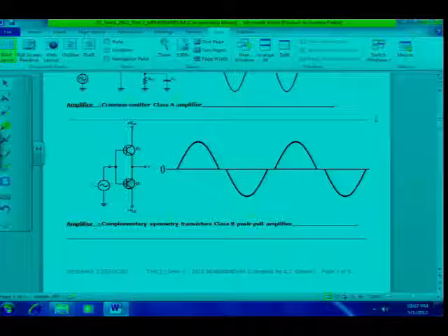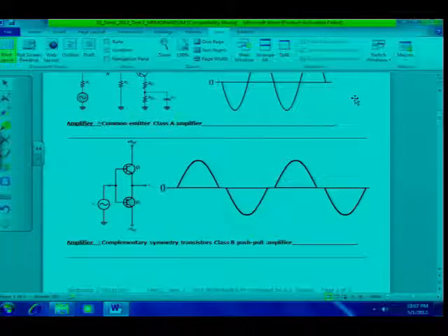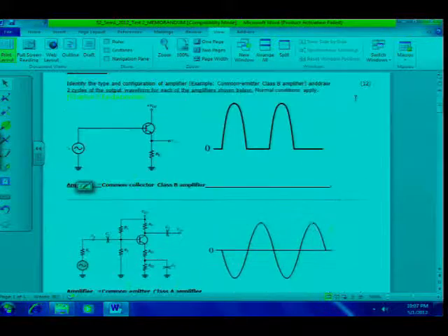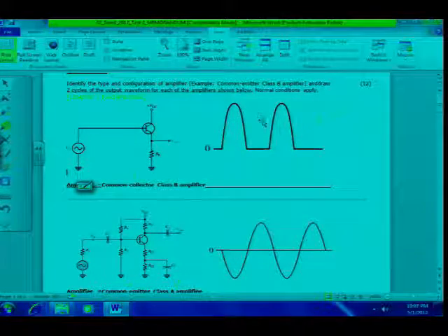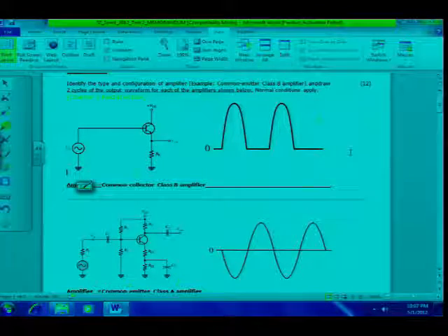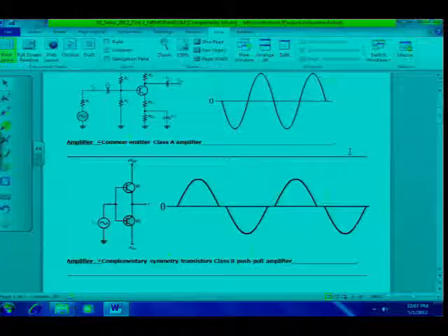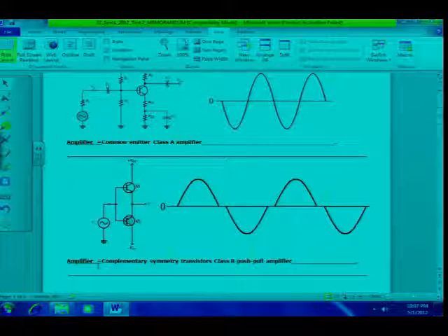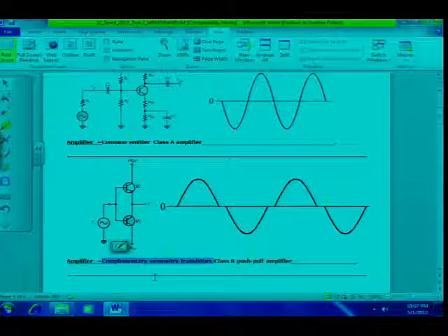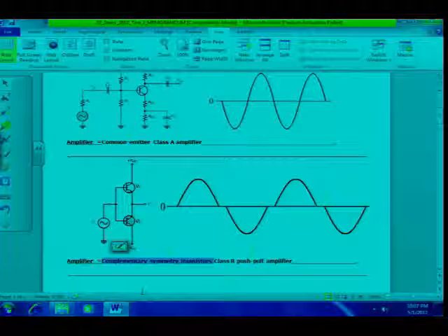The 3rd one, when we discussed the different types of amplifiers, remember we've seen the class B, but if I want to get from the class B amplifier, I want to amplify the negative and the positive alternations of my input signal, then I use 2 methods. This method of course here is the complementary symmetry transistors for 1 mark.